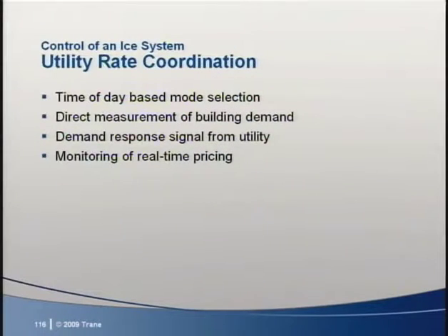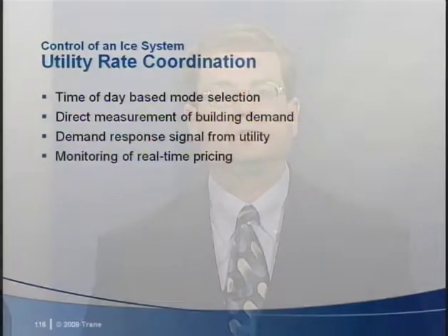The final step in engineering of the thermal storage control is the coordination of the modes of operation with the utility rate structure. This utility coordination can take a number of forms, but it typically evolves from the initial meeting with the electrical utility. The timing for mode control may be as simple as a fixed on-peak kW limit, or a time-of-day rate based on on-peak, off-peak schedules.